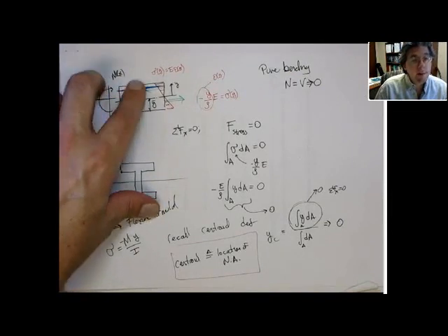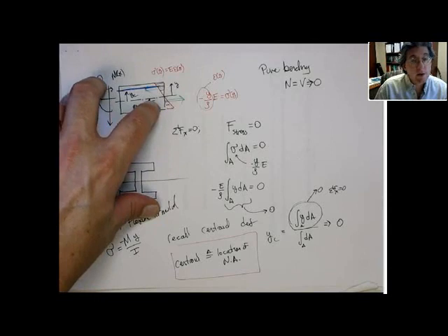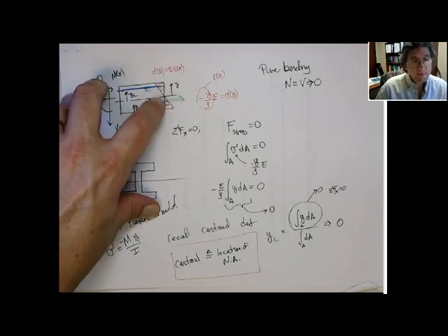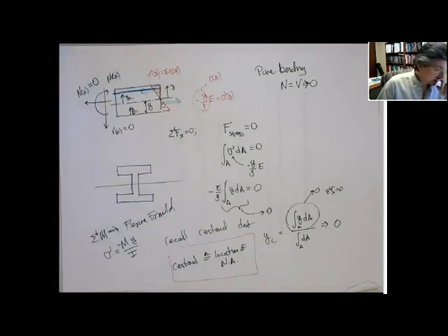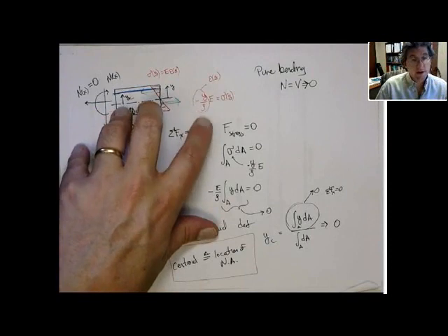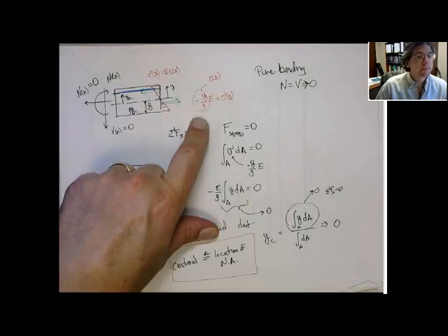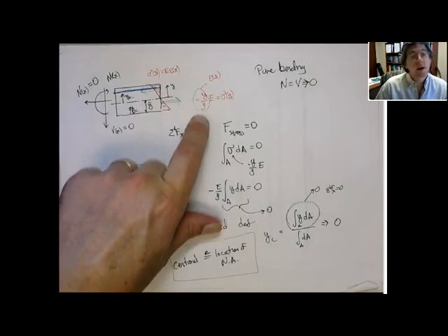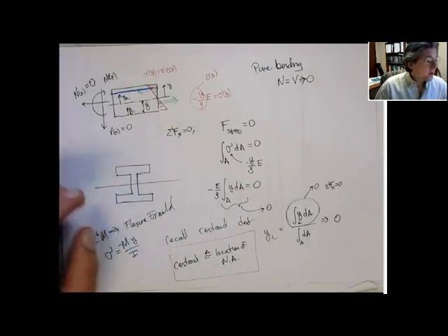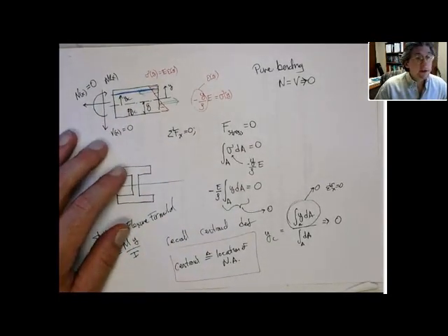tension on one side and compression on the other side. And it's quite reasonable to assume that there's going to be one location through the thickness where we transition from tension to compression. In other words, the strain is equal to zero, and therefore the stress is equal to zero. Using that, we're able to show that the strain distribution for the cross section is minus y over rho, which is the radius of curvature. I don't know what the radius of curvature is, and also really don't know the location of this neutral axis. Now, the next thing we did was we looked at sum of forces.